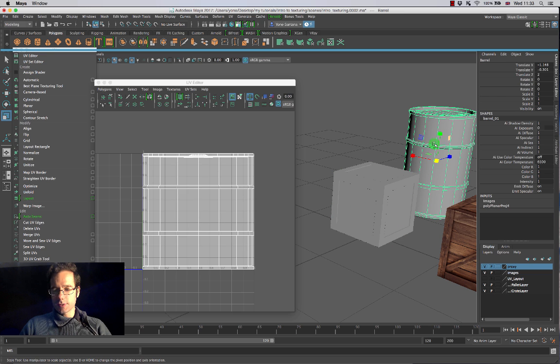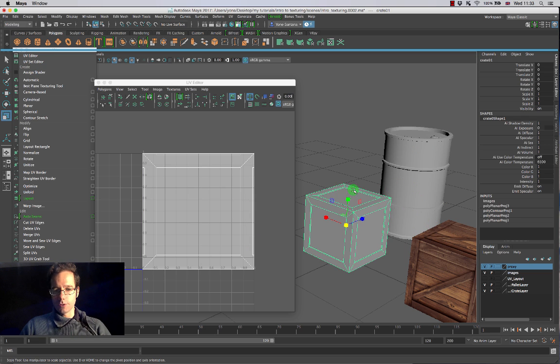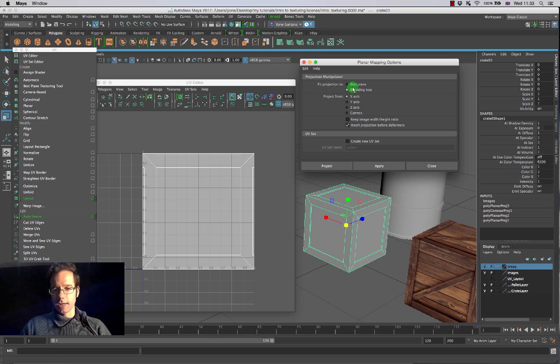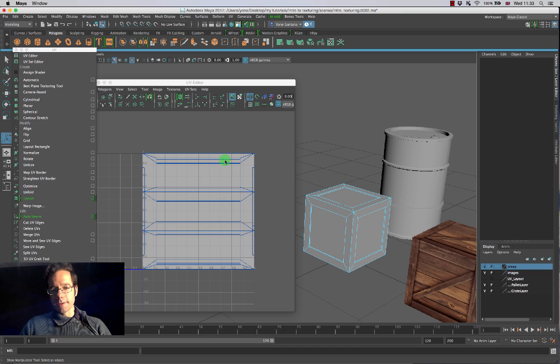And if I look at this example again, here I've purposefully changed the UVs of this object so that it doesn't really make sense. I've actually taken both of these objects, selected them, and gone into just a planar projection and chosen the best plane possible over here. And then I've chosen apply, and it's kind of like just muddled the UVs up in a crazy type of way. So importantly, you won't always have perfect UVs as soon as you create your object.